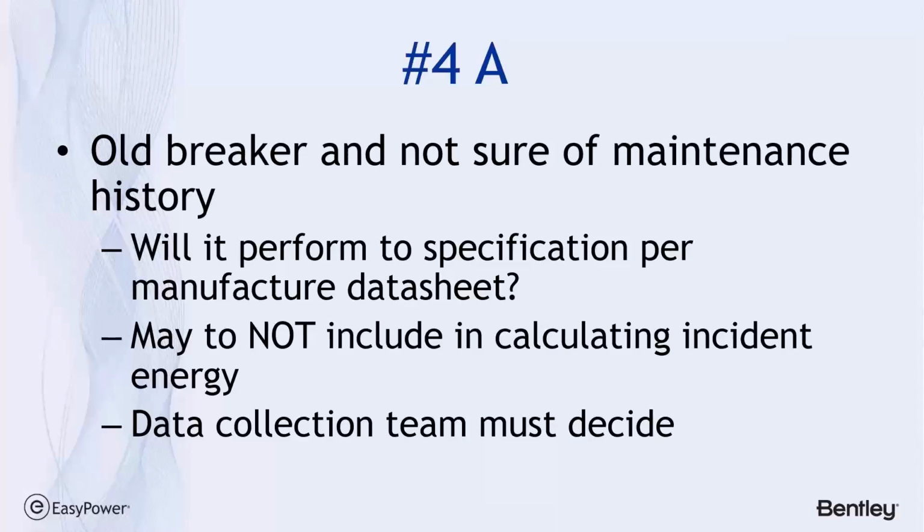Review question 4. If you have an old breaker and you're not sure of the maintenance history, and you're not sure it will perform per manufacturer's data, what do you do when you're doing data collection? And frankly, this is a task that the data collection team needs to understand, and that is they are making an assessment on the conditions of each piece of equipment that they take data on.